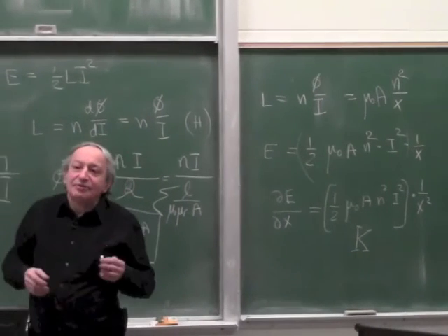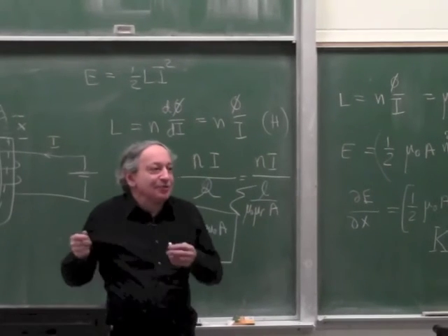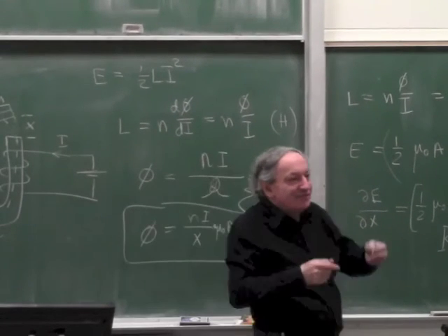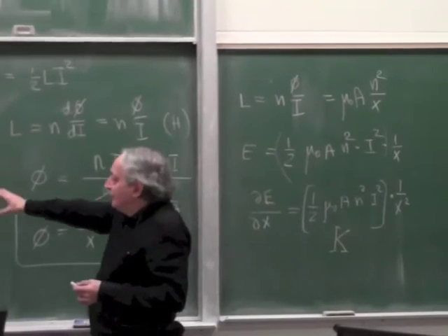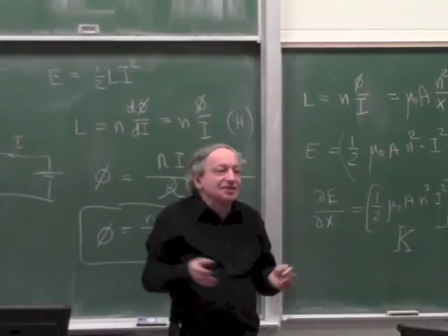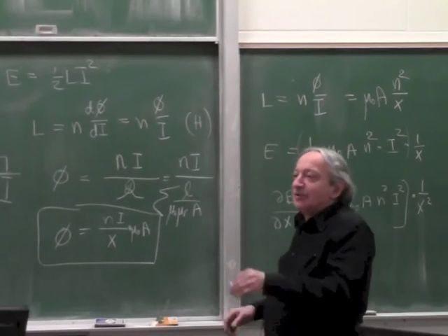Now you can say today with computers you can measure x and then change the gain, because the computer can look at x, change the gain of the servo. Basically you take this and you have a variable gain amplifier and you make the whole system behave like constant gain. But there's problems with that too, which I won't get into right now.